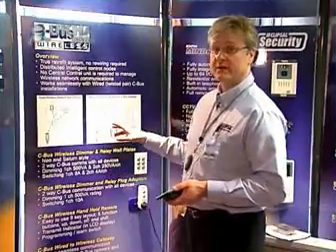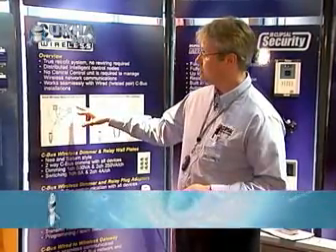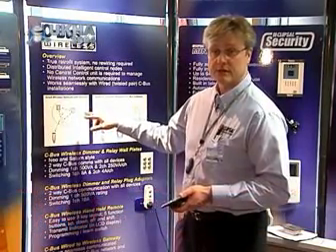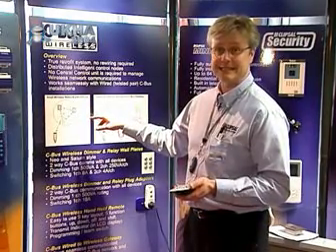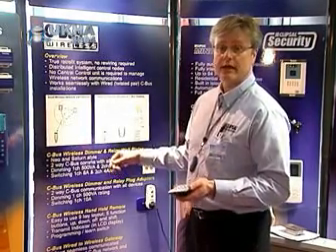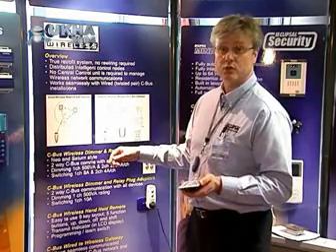CBus Wireless, one of our new product ranges, allows you to, in a retrofittable environment, remove your existing light switches and then install a CBus wireless switch. No neutral is required, and it will install and connect to an existing installation. So your switch wire and feed is just connected in the normal way.